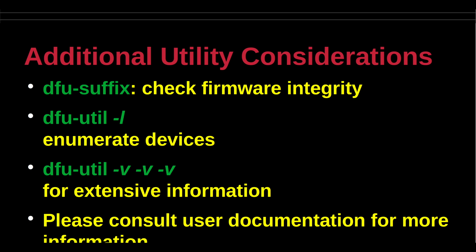The first one is the -L parameter that lists information about the device. In particular, some useful values like the vendor and product ID pair and alt setting information can be obtained before using these actual values to flash the board. Finally, there is the -V option to log extended information that may be required by the developers of dfu-util to assist in debugging failures in flashing the firmware.